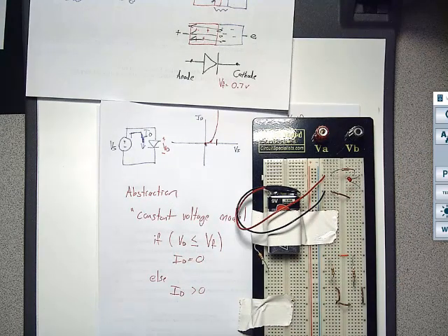Here is what this means. You are going to increase the voltage of the source starting at 0, and no current will flow. As soon as the voltage gets up to the point where it meets this forward voltage spec of the device, this will turn on and current will flow. That's all that says. The second thing that's key with a diode is that the voltage across it clamps at that spec. That's what's great. That's the cool behavior of the diode.